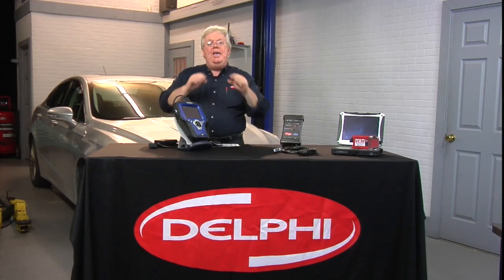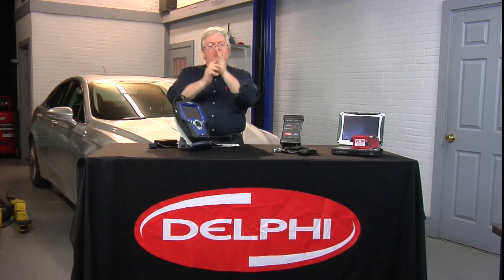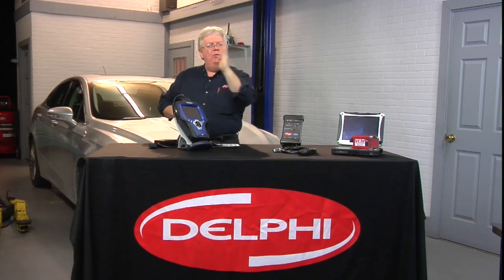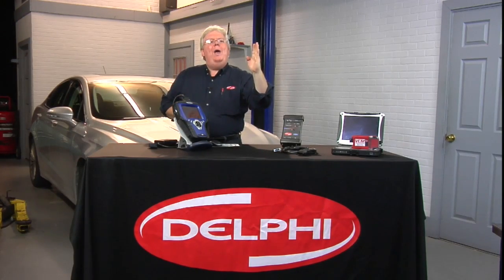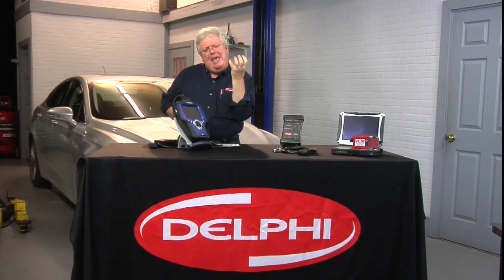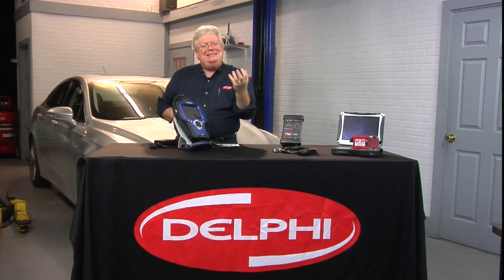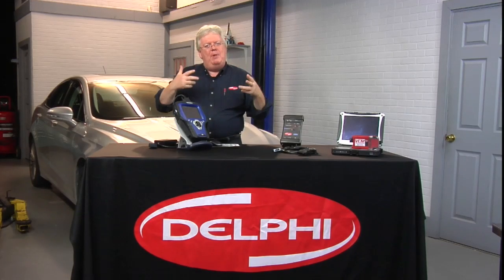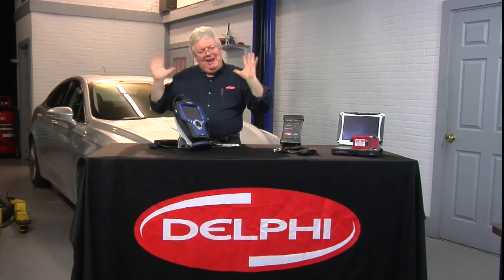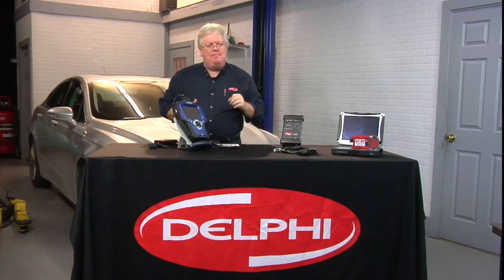Toyota will work well with all of them being the pass-through between the Toyota, Lexus, or Scion vehicle and your laptop. Not only factory scanning, but it does a really nice job on mode 6, complete with a color-coded bar that shows you visually at a real quick view where the parameter fell when that monitor ran, and we did that snapshot in history of what was going on with the mechanics, the details of the monitor, all the various tests that have to run for that monitor to say, I ran that test on some particular system.